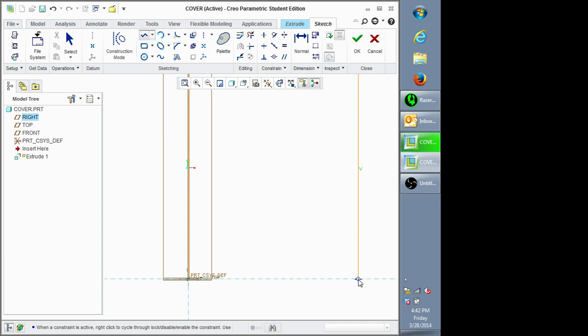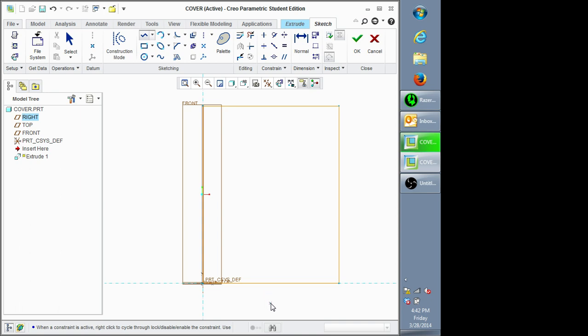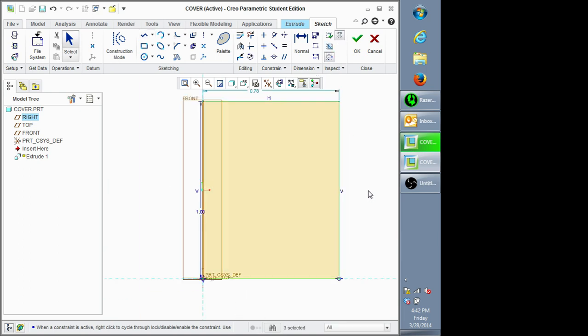There we go. So select and make sure it's along this. It locks on this bottom edge too, because the constraints can be very important. And it might be hard to see, but it should lock onto this point down here. So just select it. There we go. Okay, so we do a middle click and we'll leave it. And see that's kind of shaded? That means that all is good. It's locked onto all the points that you want it to.